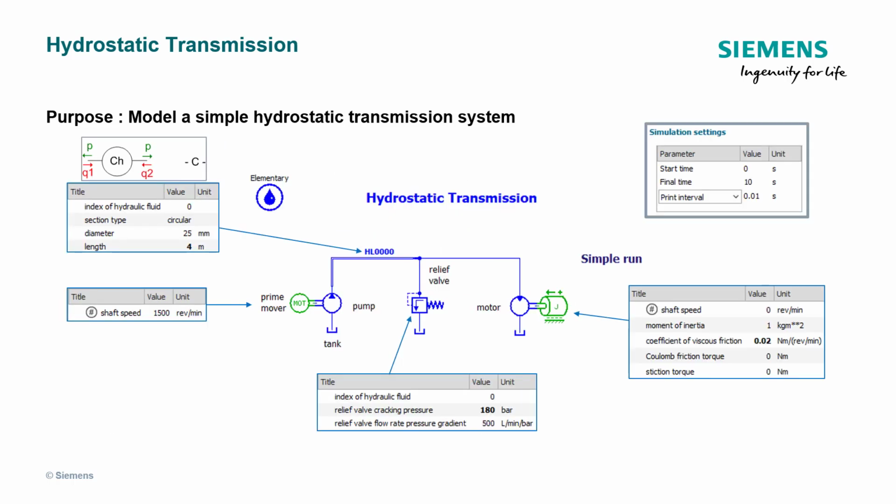From the HYD library, select the components as shown in the MC model in this slide. The fluid property is set with the elementary option. Based on the parameter values shown on the previous slide, we can input them directly in each component. Please note, for the pipe component, you need to first switch to submodel mode and click the direct line. Then you will be able to select a different hydraulic line model for this pipe. Please make sure you use the line submodel named HL40, which will consider only capacitive effect.